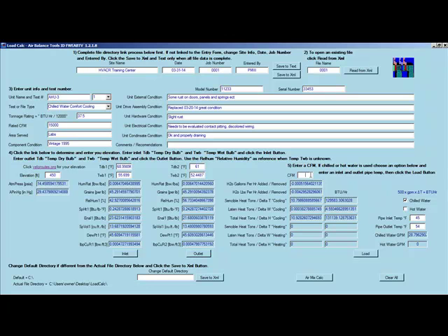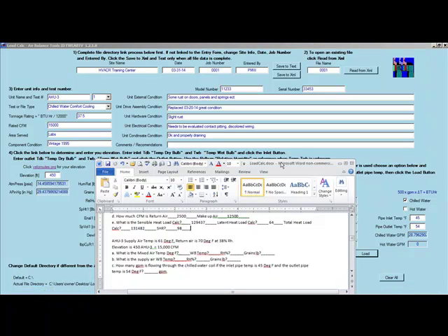Close enough for me, so we're going to go ahead and say 15,000 CFM. The load calc, our chill water coil is delivering 28.79 if our inlet pipe is 45 and 54. So let's go ahead and finish the rest of this.